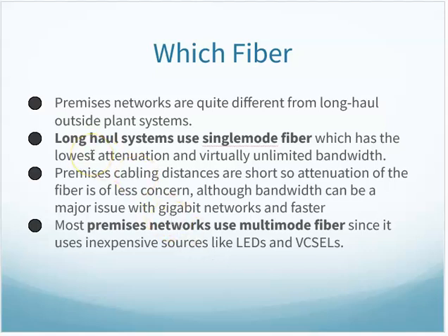With long-haul systems using single mode, this would be maybe where you have a cross-campus connection. I always think of Penn State, where the campus is pretty widespread. So as you start connecting buildings, you might be using single mode to go from a main building over to the other side of campus and so forth. So inside of a building, most likely multi-mode. As I start connecting buildings, I might be moving over to single mode.